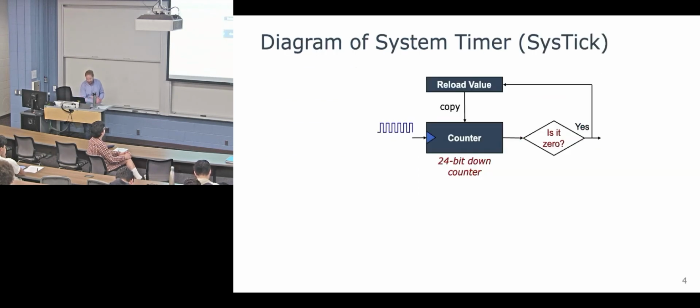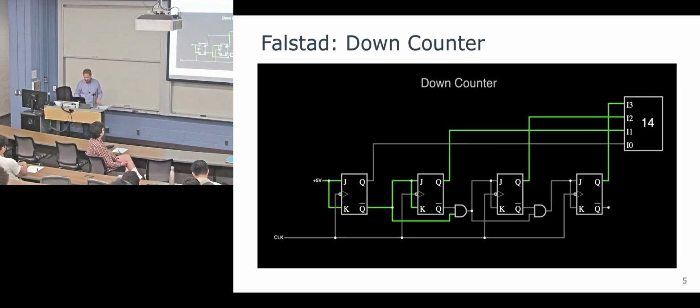So just like before, it doesn't have a capture compare register necessarily. It's just a down count timer, 24 bits, and it's going to set up an interrupt after it gets down to 0. You can go through the schematic if you get excited, but basically it's not much more complicated than a bunch of D flip-flops and AND gates that consecutively count down.